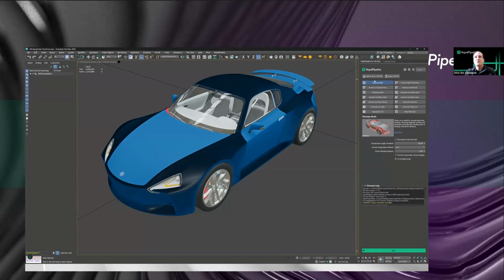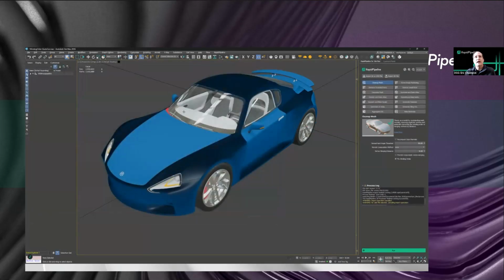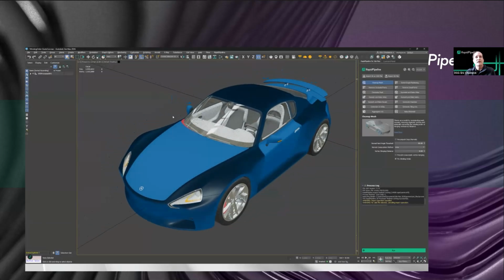And thankfully, we have a tool. It's also in the import options, but you can also use it after you've imported the model and done your material work. We can go ahead and use this option called Fixed Winding Order. Basically, it's going to run on whatever's visible in the scene. I don't have to select anything. I could select individual parts and say only the winding order on those selected parts. But here, with nothing selected, it just automatically takes whatever's visible and does its processing on that.